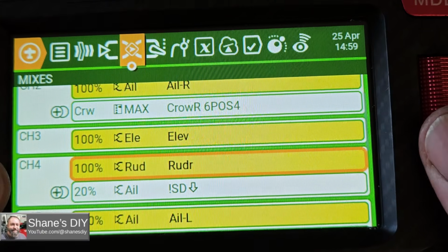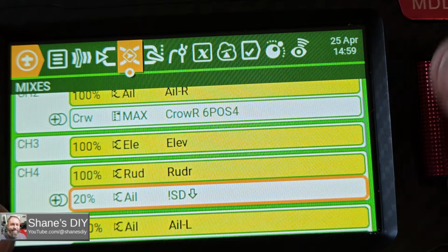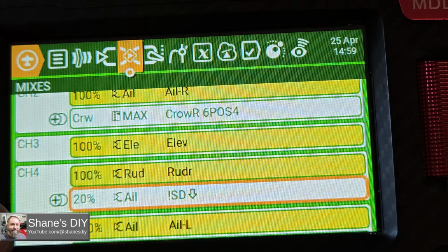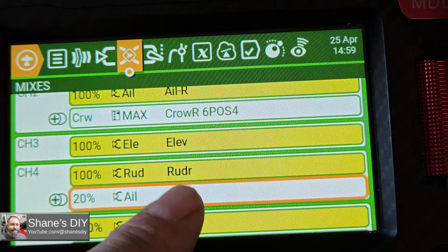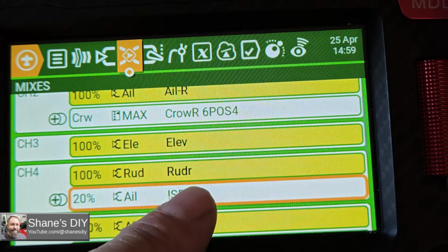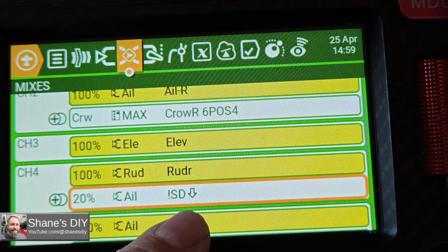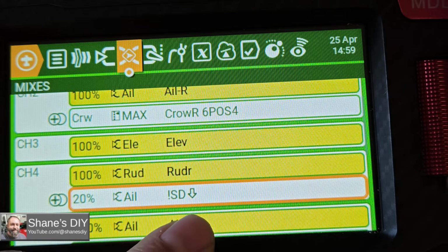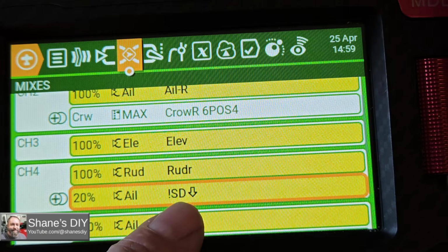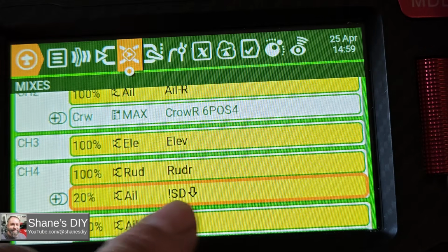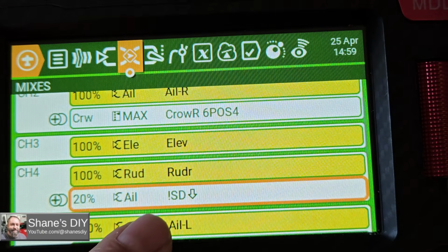Okay, now channel 4 does have a rudder to aileron mix built in there on the D switch. Basically, if the D is not towards me, I'm going to have a rudder to aileron mix. The viewer wanted a kind of aerobatic mode to get rid of that coordinated turn thing in case you want to do aileron rolls and such. So towards me, that was off. If I go in the middle position or forward, both of those have the rudder to aileron mix activated.